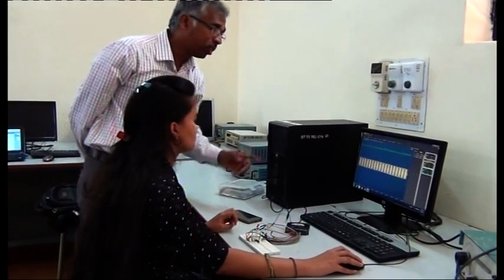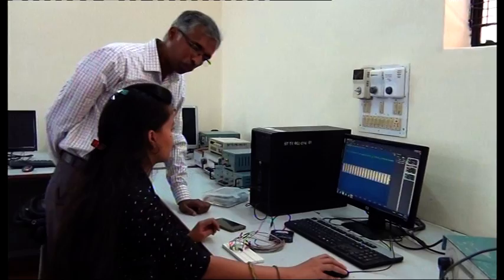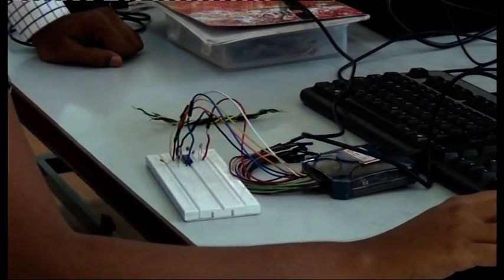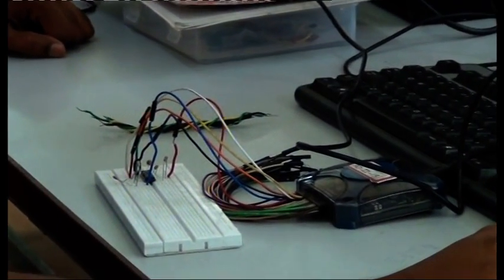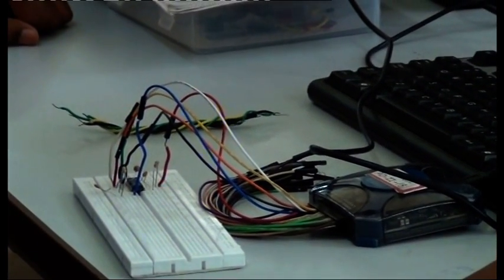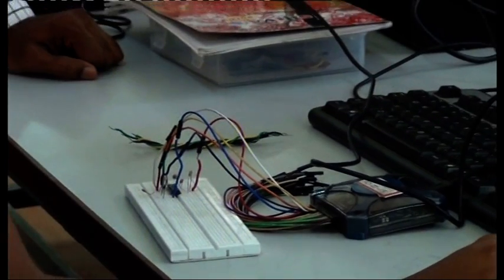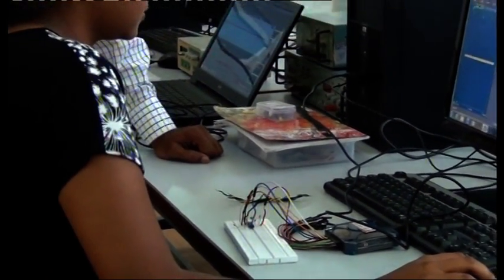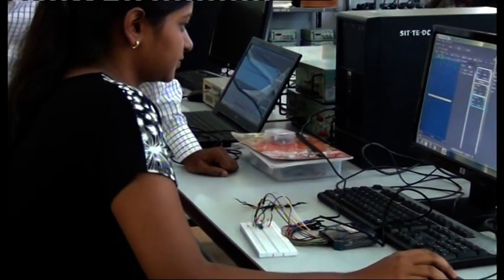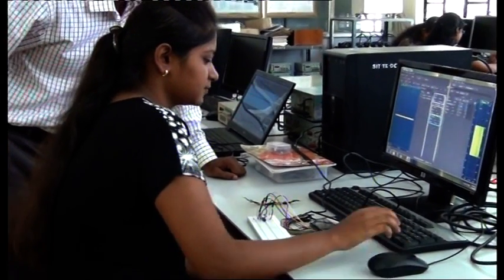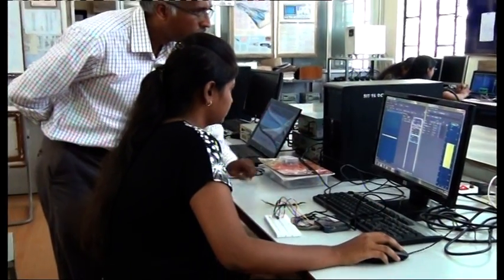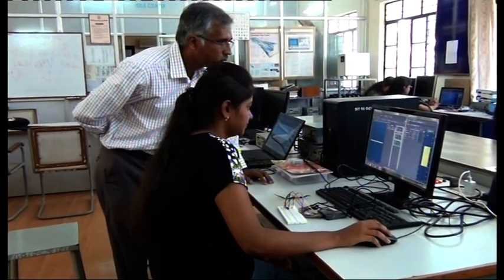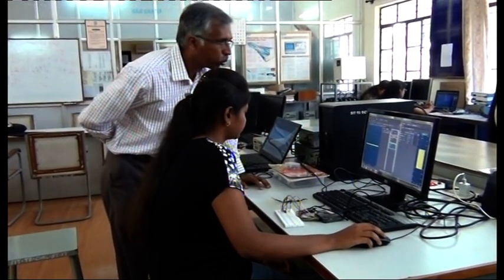Okay, now the carrier frequency has gone out of the capture range. Change the modulation index. Make it 50%. It will go out of the lock range and not demodulate. So up to 30%, make it 30%. 20% of it is out of range. So 20% is fine. Make it 20%. At 20% you can demodulate.